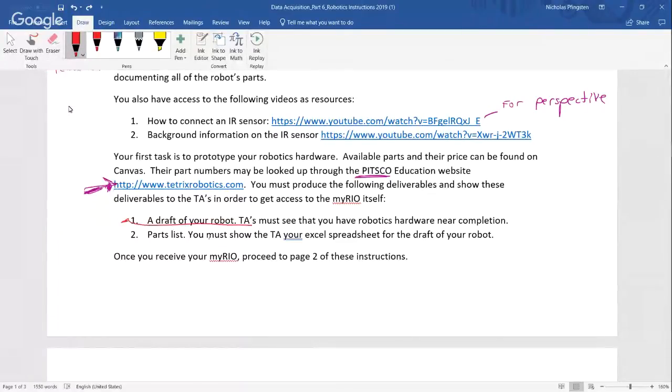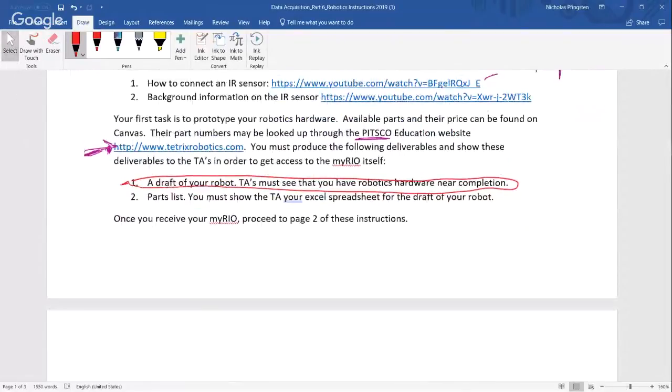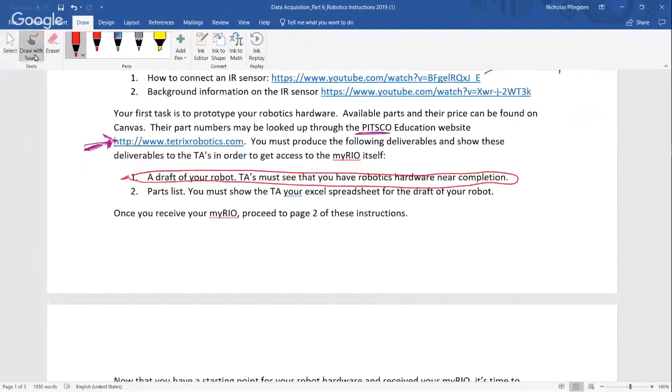In most of the robot designs, there are really two approaches that people have used. One is differentially steered, which means you have a servo and a wheel on each side, and depending on how fast each side spins, that determines the behavior. The other approach is just like a traditional car.